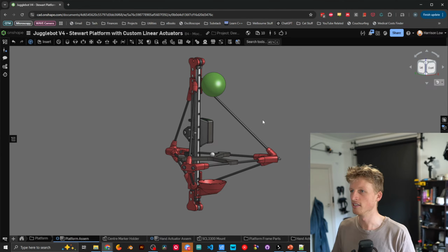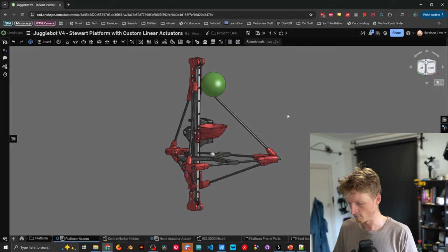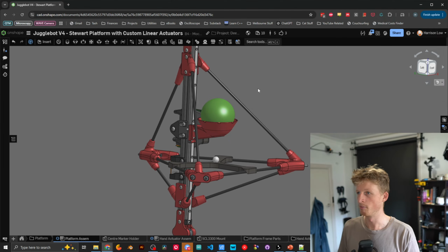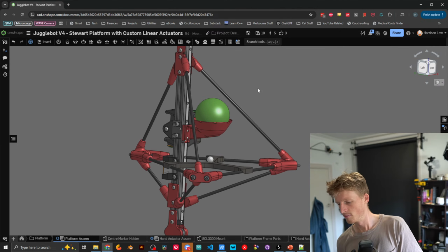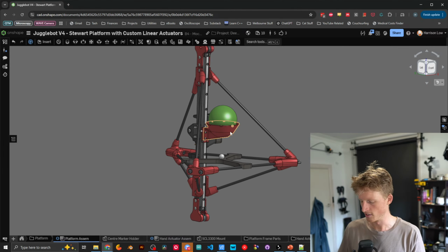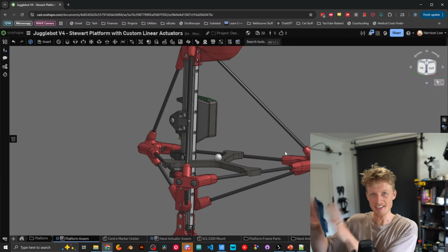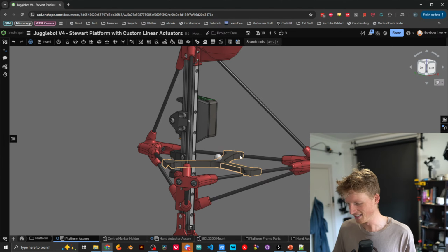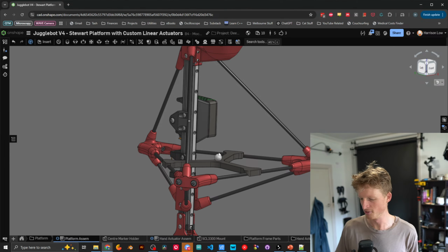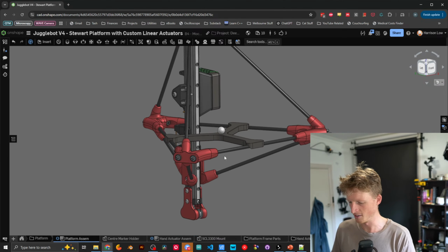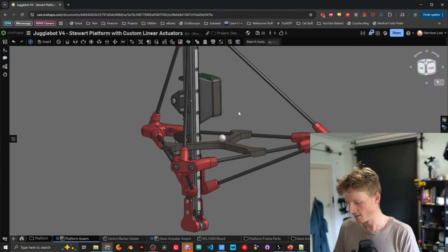Now, I think what John is suggesting is to put a ball in the hand in the center of the stroke. So that would be, I don't know, there-ish. And then use that point to be the platform coordinate system. I can see how that would be helpful for the hand, but I think I'd prefer to leave all of the inverse kinematic stuff as clean as possible by having the base centroid in line with where the legs attach to the base, and the platform centroid in line with where the legs attach to the platform. I kind of like that.